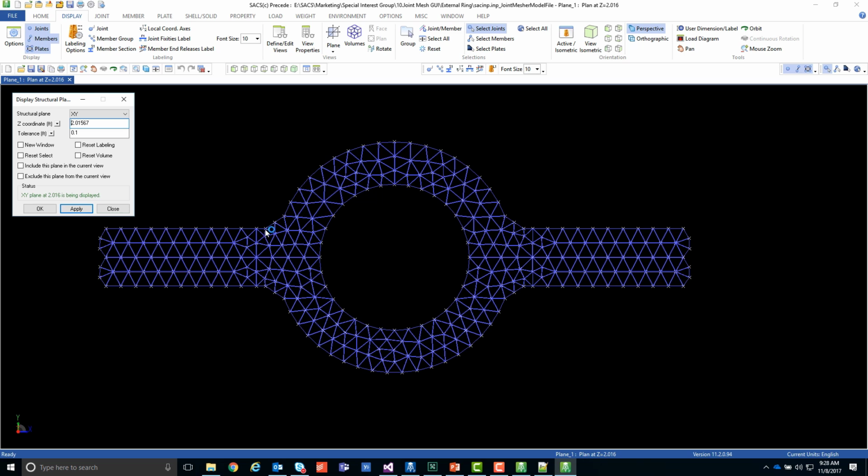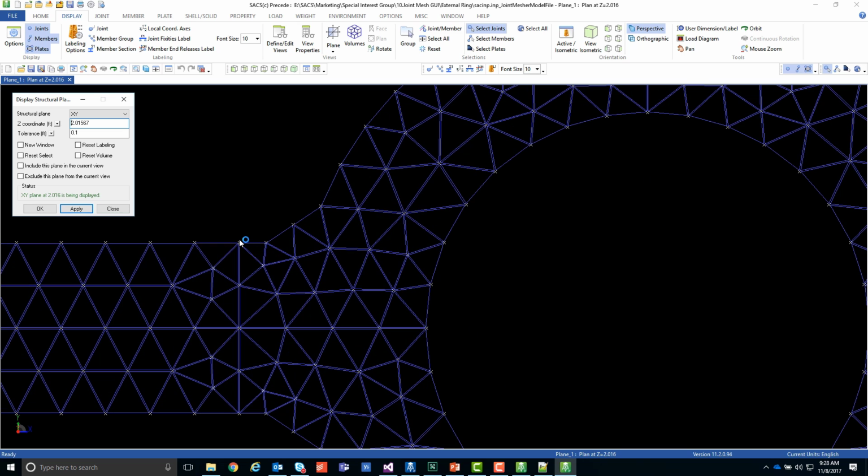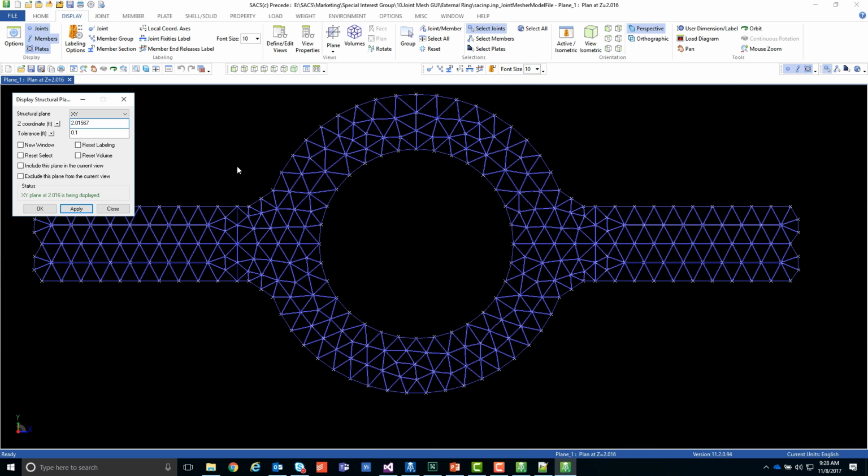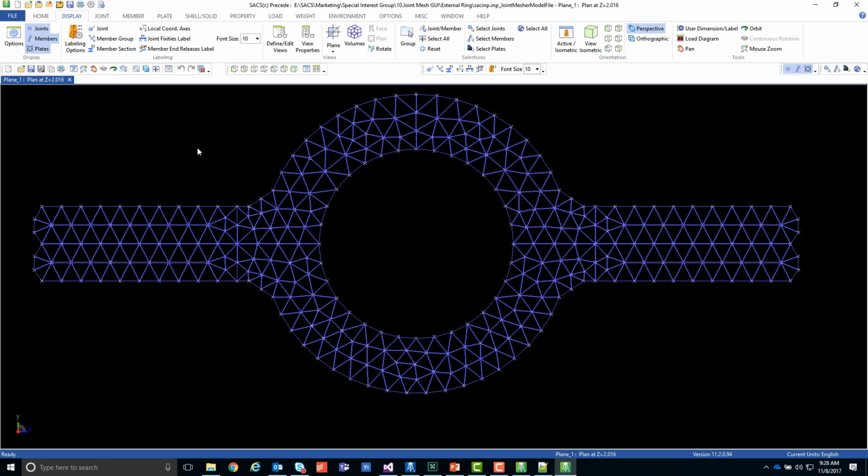We may want to increase the mesh intensity or decrease the element size, because that arc transition looks a little flat there. Might want a smaller mesh size to get a better representation of that. But generally this is pretty good. So let's see. We'll go back,